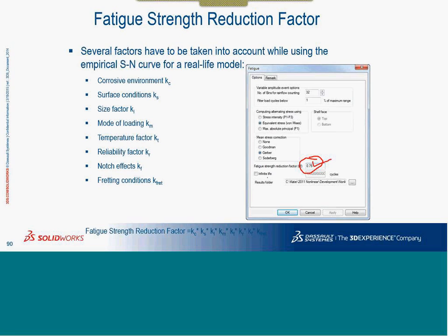Second, in terms of infinite life, we are talking about 1 million cycles. If you have observed, if the stress levels are too low, sometimes the results that come from fatigue analysis are meaningless. Many do not understand it. But the fact is, this value as well, we are specifying that if the stress is below a certain value, there is no point in showing results. It is actually infinite life.